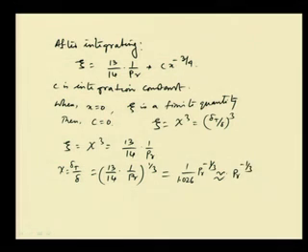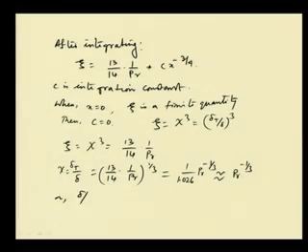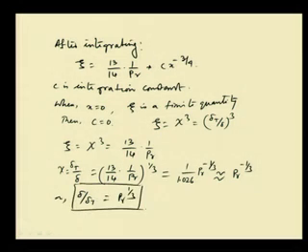So, that is what we have already seen, that the ratio of thermal boundary layer thickness to the hydrodynamic boundary layer thickness is equal to Prandtl to the power minus 1/3, or delta by delta t is equal to Prandtl to the power 1/3. This we have also used previously for some of our understanding, that delta by delta t is equal to Prandtl to the power 1/3, and for Prandtl number equal to 1, delta is equal to delta t.